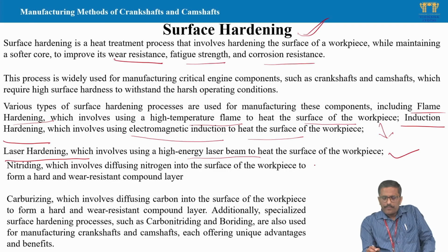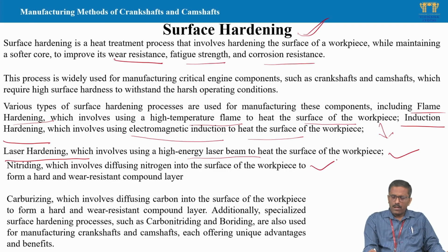After that, we also go for nitriding process and carburizing process. Nitriding process means we introduce nitrogen gas onto the surfaces so that a nitrogen layer forms on the surface, so that the surface becomes hard as well as wear resistant.